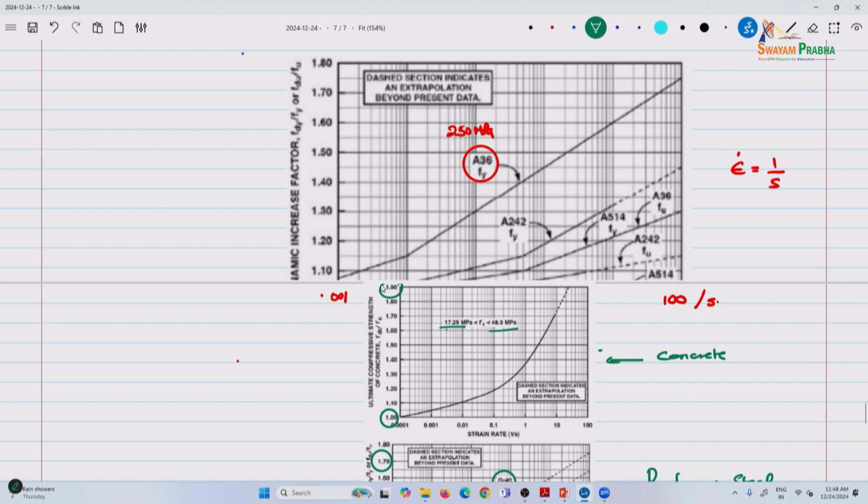Are there any reasons behind this increased factor at high strain rates? Yeah, materially the material hasn't had time to change its molecular structure. For me, I try to use some simple examples. If you pull something really hard, it's so hard to pull it instantly, whereas I can take the same thing and slowly keep increasing the load. That's sort of the strain rate effect. If I make a slow pull over time, I may be able to pull it apart.